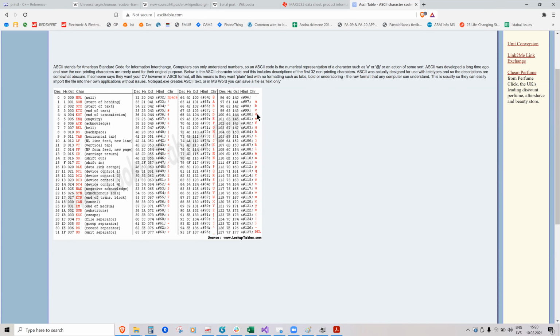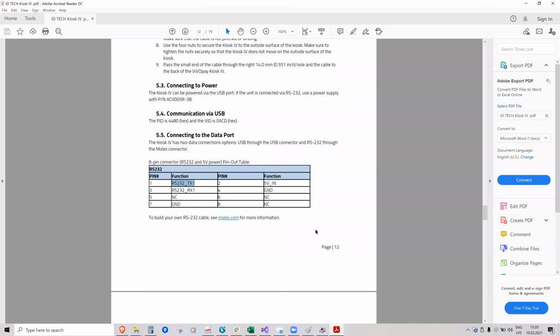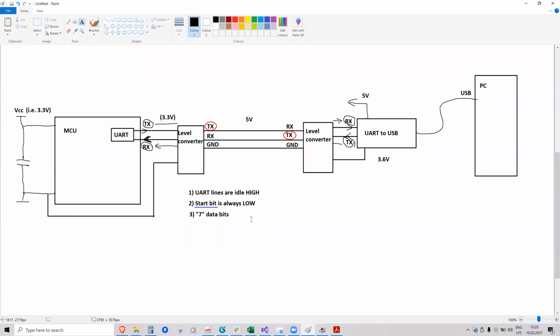In the English language, all the letters, all the brackets, delete button, space, exclamation mark, everything, new line symbol, all of these symbols, there aren't really that many, and it's just 127 different symbols. You can fit them, 128 different symbols counting from 0. You can actually fit them all in just 7 bits. So initially, UART actually used 7 bits. And here is why. Another reason.